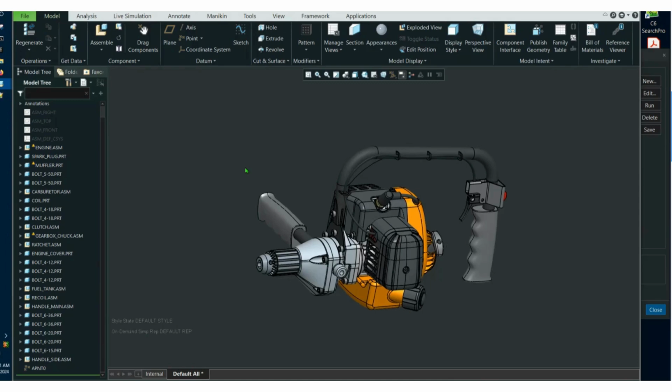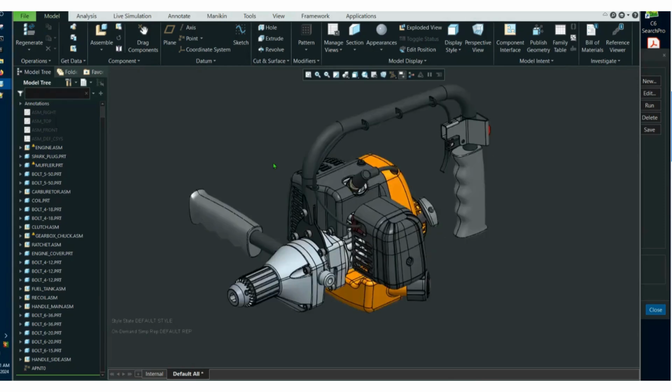If you record a bunch of nonsense into your map keys, they do not port well between versions. I have map keys that I've literally been carrying through versions of Creo that are fairly complex, that I have utilized for well over 10 years, 10 to 15 years, and the map keys still work today just like they did then, but I took some time to make sure they were recorded sanely.